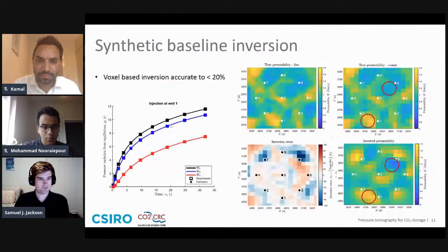So when we do that, we end up with these results. So the pressure data for well 1 and the monitor data is shown here on the left-hand side. The squares are the experimental data, and the circles are the inversion response. So when I say experimental data, I mean the data here from Eclipse. And you see it's essentially a very good match. It's almost perfect. And to get this fit, we've had to vary the permeability.